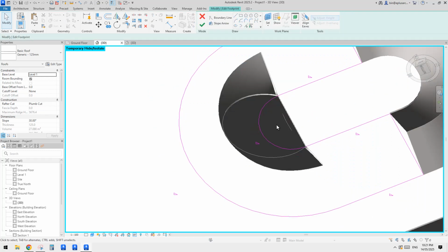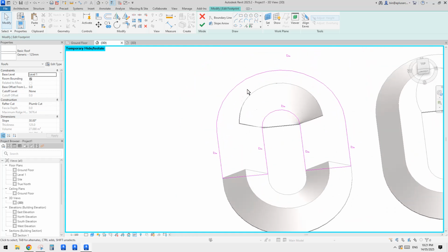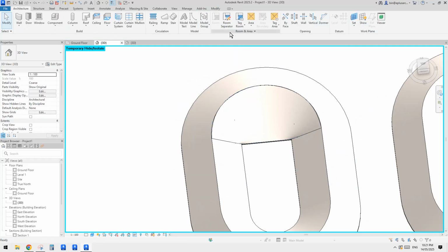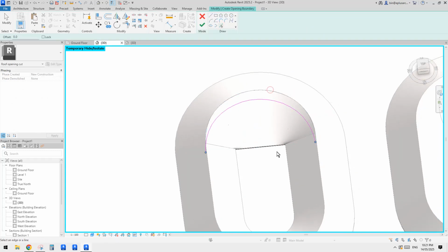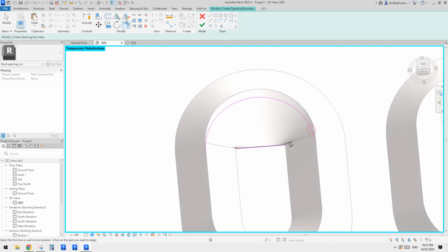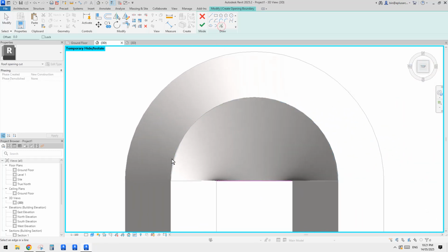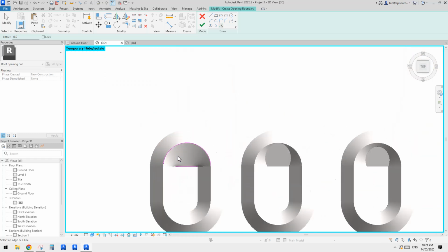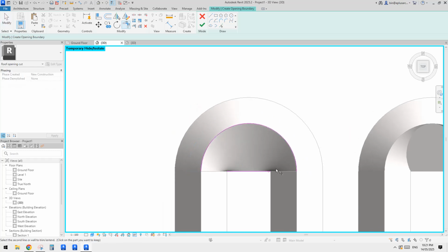If I do this, how do I cut this off? Probably that won't work. Yeah, we shouldn't change the footprint. Maybe it's probably easier to just do a vertical cut. So let's just do a vertical cut. I'll just pick the ridge line, pick this edge, trim. Oh, hang on. So this is spline, we can't trim. So I'll see if I can pick the edge of the roof. So this one, which is arc instead of spline, so you can see there's one circle control point here. So it's an arc instead of a spline, which means we can trim.